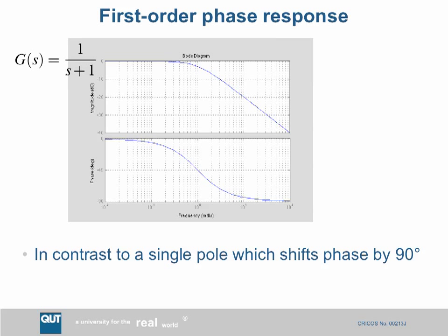And this is why it's very destabilizing. So if you think of it in terms of gain or phase margin, it's very destabilizing because the phase error just keeps increasing. So a delay has got a very interesting characteristic as far as phase is concerned. So you need to take this into account when you put a zero-order hold in your system.